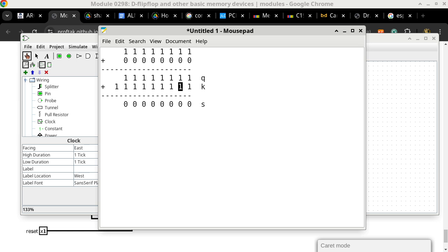Yep, exactly. And relating this back to the watchdog, remember, something is supposed to hit the watchdog every so often. Inside most computers, I would say inside all computers these days, inside the processor is a device called a timer. A timer is like what we saw earlier, except it counts down instead of counting up.